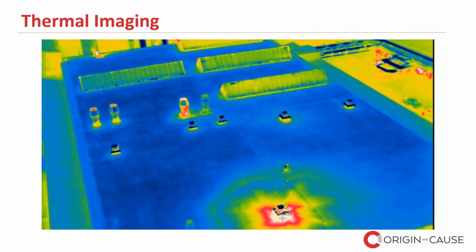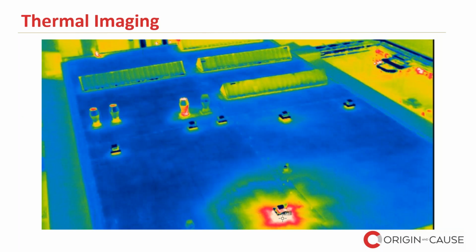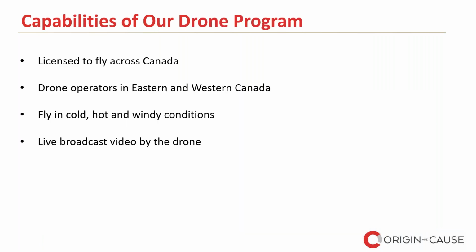Very sensitive. As well, what we can do is map a scene in the thermal spectrum. What you saw was the RGB spectrum, so the red, green, blue photograph. In this case, I can map a site to see heat loss and water penetration and use that if we're doing a building inspection as well. So it's very useful, certainly in the wintertime as well.